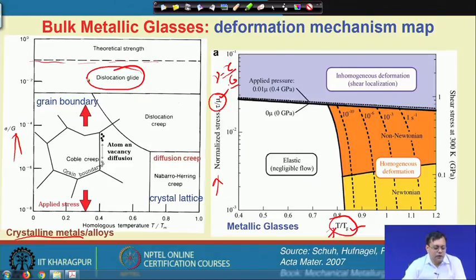However, if the strain is somewhat relatively lower, then we can think about a higher temperature, then some grain boundary process or dislocation creep will appear, or maybe if it has a relatively lower stress value, then we can also go for some sort of diffusion creep, where low stress is required for activating this process, because this ratio has a lower value along this direction.